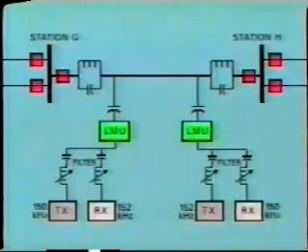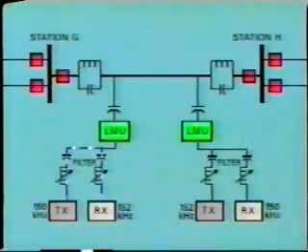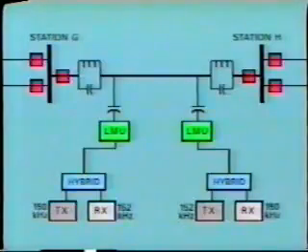Unfortunately, when the frequencies are so close together, some of the 150 kilohertz transmitted signal will leak through into the receiver. Even a very weak 150 kilohertz signal may interfere with the incoming 152 kilohertz signal and cause misoperation. In order to reduce this loss, the transmitter and receiver at each end are coupled through a hybrid unit before connection to the tuner and coupling capacitor.